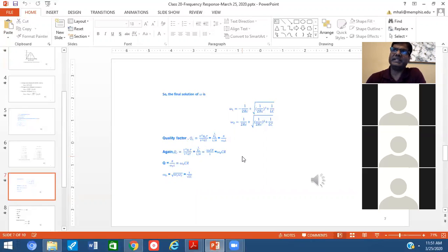So remember this symbol stands for susceptance for a parallel circuit, and BL is because we are looking at the quality factor for the inductive circuit. Then it is multiplied by T, which is the time period, the overall cycle of that waveform. So reactive power in the inductor multiplied by the time makes the reactive energy.